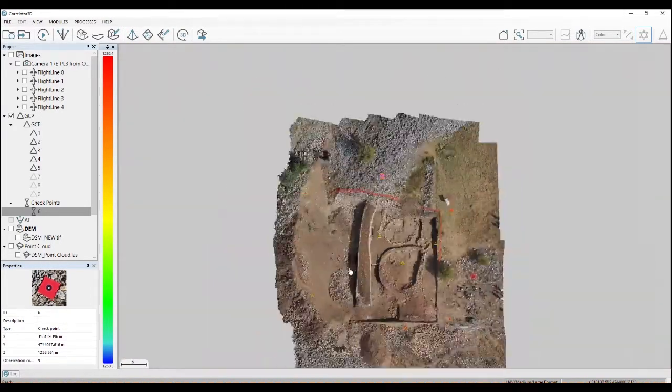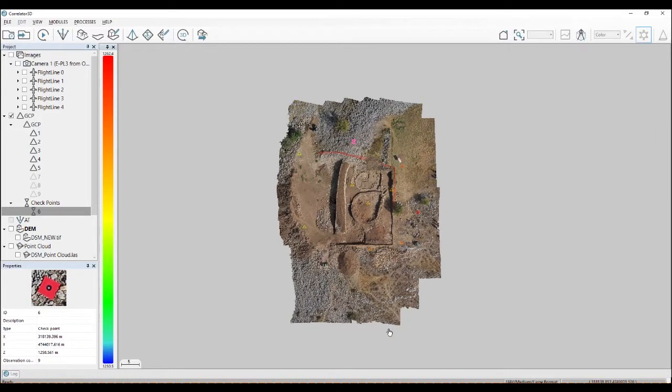Another thing you might want to validate after the mosaic is created is its radiometric quality. So how good the color balance and contrast and brightness are. So it's maybe a little more subjective. So the best way is to probably pan into the mosaic and try to look for any apparent seam lines or color problem that there might be.